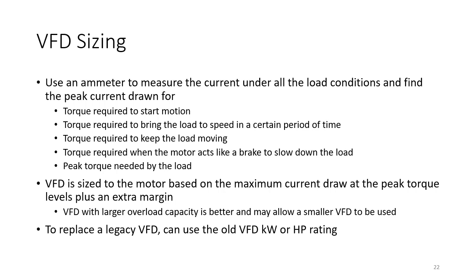So again, you might look at the torque required to start the motion. That might be quite high, but once the load is moving, the torque might be reduced. So again, you can size your VFD accordingly based on both the torque required and the current required to keep the load moving, as well as what's required to start up. Newer VFDs tend to be better for that, and paying more money for a VFD will give you better characteristics. But of course, you don't want to spend too much on your VFD. Another possibility is specifying a slightly smaller VFD, as long as it's got the correct startup characteristics. That could also help save money, because you could go down the frame size on the VFD but still get the performance you need.